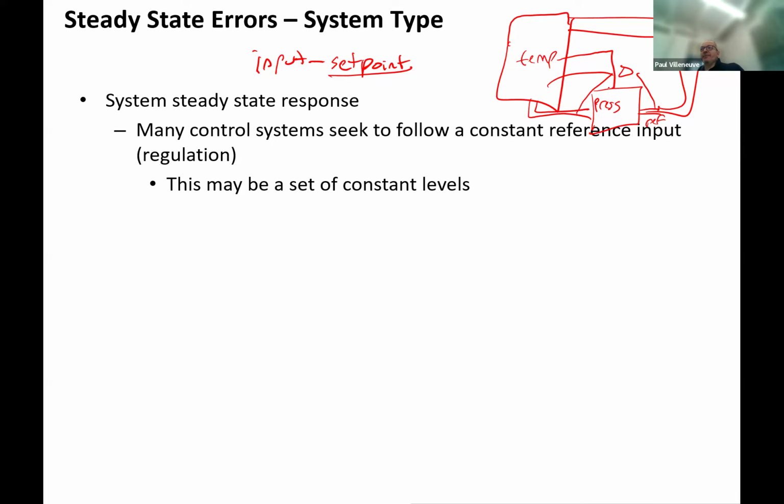Yes, sir. Would you adjust density of a constant material to temperature though? Is that why you enter temperature? Yep. If the temperature inside the tank isn't going to change all that much, you might not necessarily need to do that. The ones that I've seen typically have temperature correction.